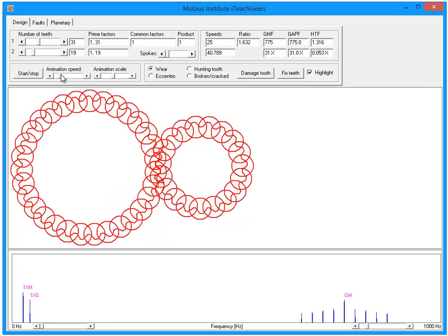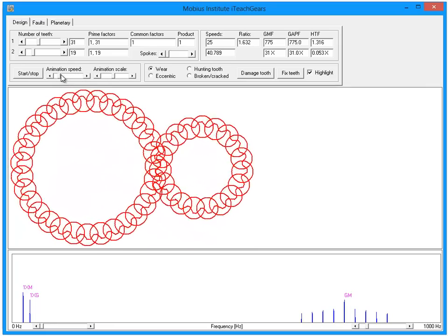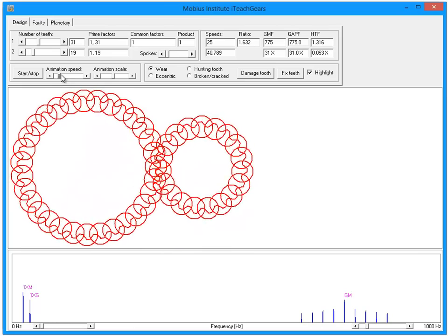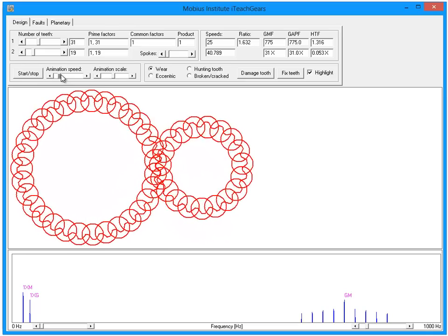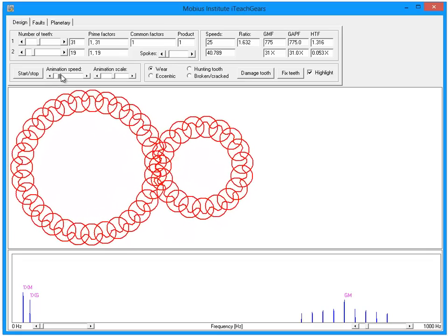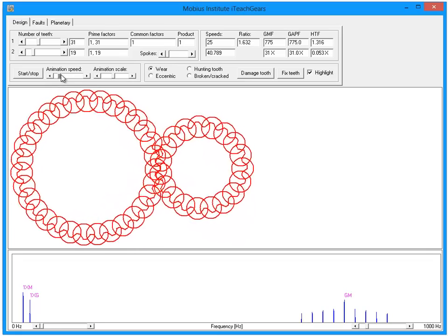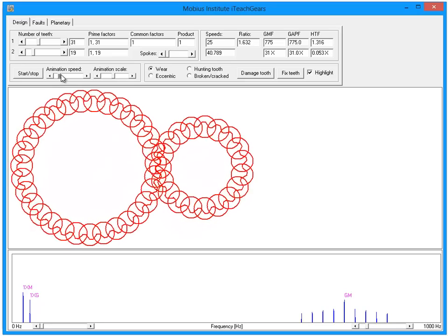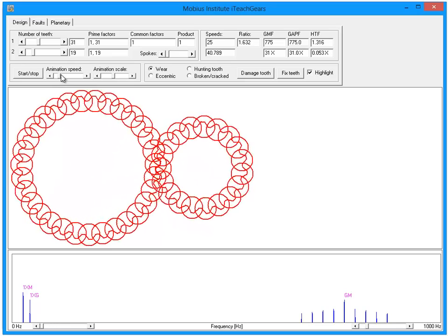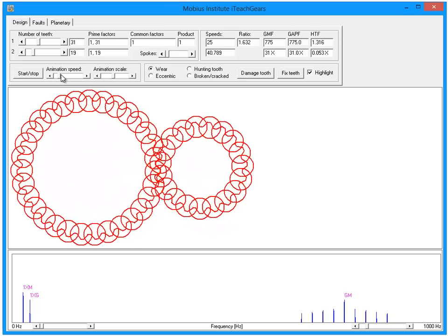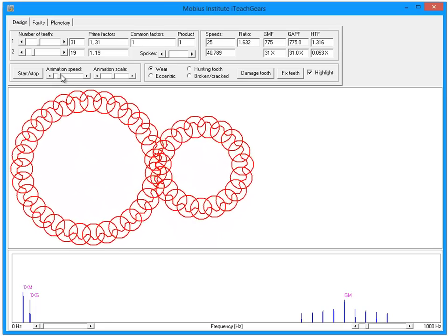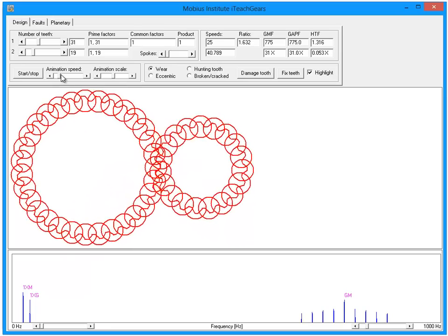Now that means that if any tooth is slightly damaged for any reason, it may be that the lubricant is contaminated. It shouldn't be, but let's say it is, and some hard particle goes through and slightly damages the tooth, and that makes that tooth imperfect, and then that mates with the tooth on the mating gear, and that has the potential for slightly damaging that tooth. And as you can imagine, these gears are just turning, and so this is just repeating.